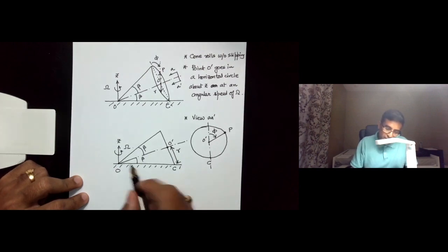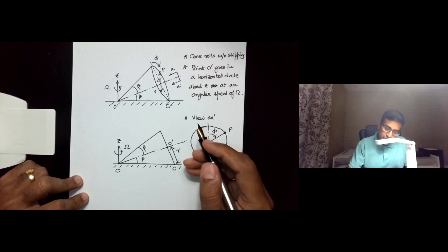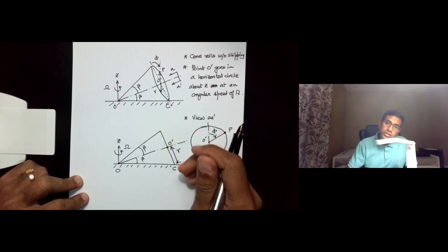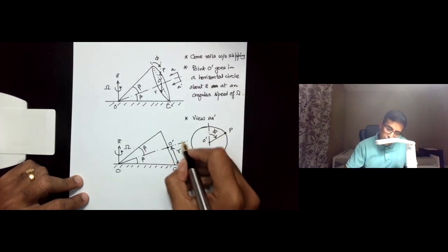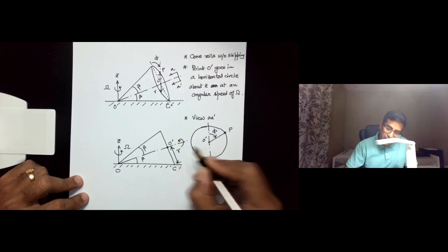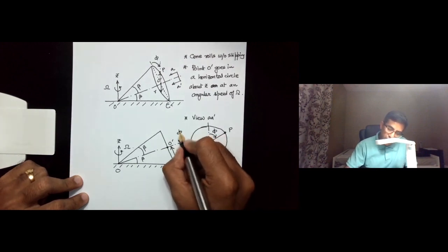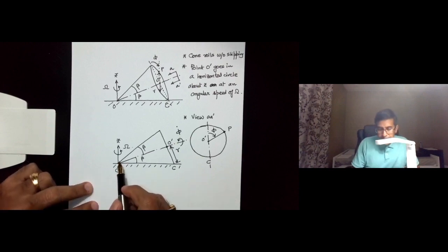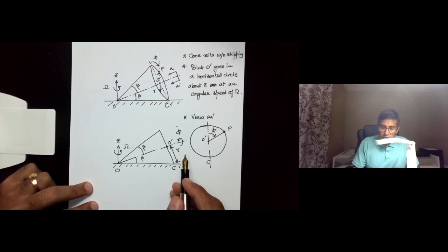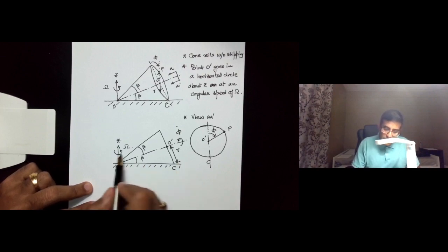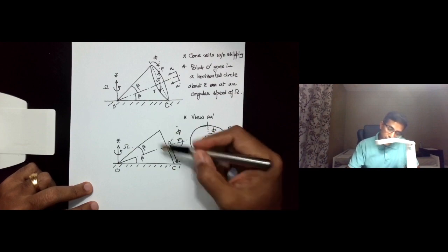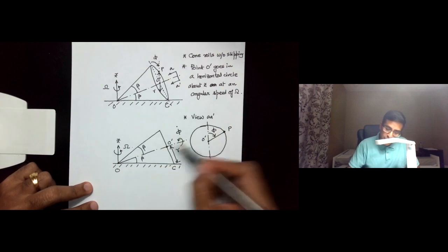Now, for the sake of completeness, in this diagram, I'm going to say that as the cone rolls on this horizontal surface, you can see that the base circle of the cone is turning in this manner, with an angular velocity of phi dot, which basically means that the cone, because of its roll without slipping, as it turns about this vertical axis with an angular velocity of omega, the cone itself spins about its axis.